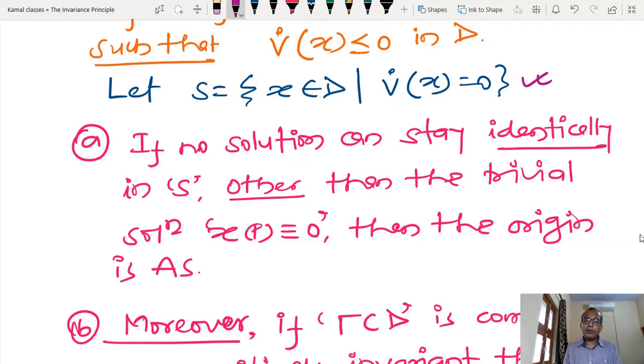I have taken a Lyapunov function that is positive definite, V dot x I have created like this, and after that I know that (0, 0) is going to lie inside some kind of region, and the region I have already defined: x1 lies between -pi and pi and x2 may be anything. Okay, so I have some kind of bounded region I can create by truncating x2, then this kind of condition will hold.